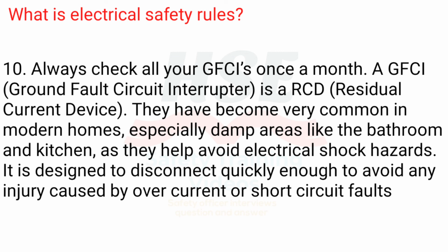A GFCI, ground fault circuit interrupter, is a RCD, residual current device. They have become very common in modern homes, especially damp areas like the bathroom and kitchen, as they help avoid electrical shock hazards. It is designed to disconnect quickly enough to avoid any injury caused by overcurrent or short-circuit fault.